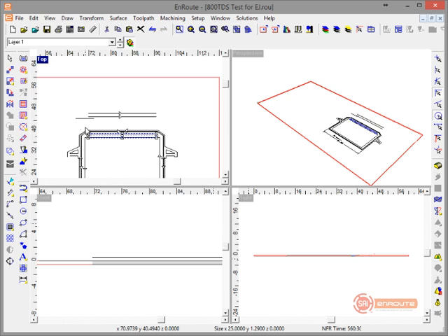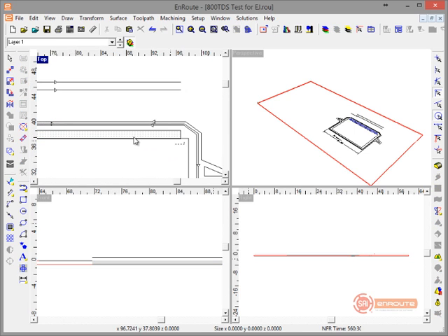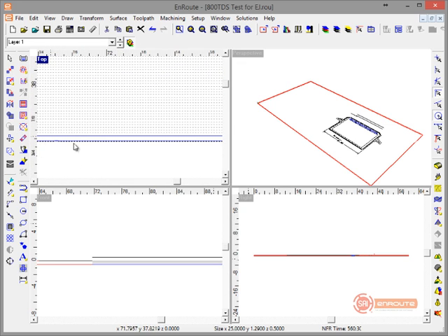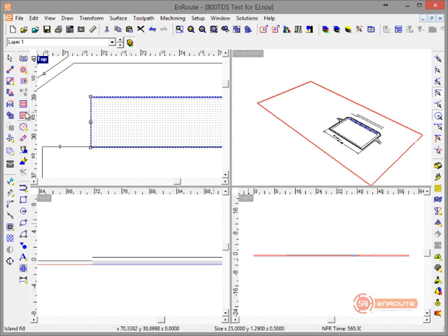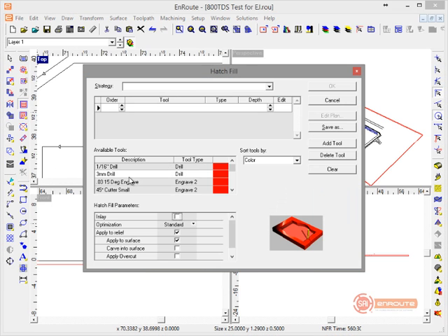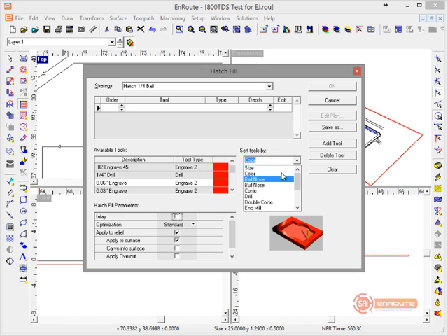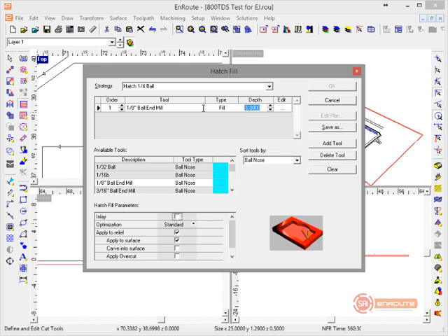So now I'm going to select both the relief and those little lines that I offset, and you can see it here. It's even going to extend just a little bit past here, the toolpath. Now let's do a hatch fill here, and this is where you'd have to decide just how detailed you want it. I'm going to go to the ball nose tools, choose 1/8 inch ball. That'll give me a 1/16 inch radius on those sides. I'm going to say 0.5.